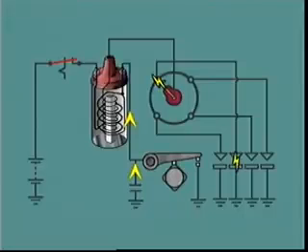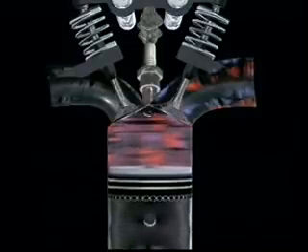The capacitor then discharges back through the primary circuit, causing further induction, a continuation of the spark at the spark plug, and another charging of the capacitor. Current continues to oscillate in the primary circuit until all the energy in the system is exhausted. This will maintain the spark at the spark plug for about 2 to 3 degrees of crankshaft rotation.